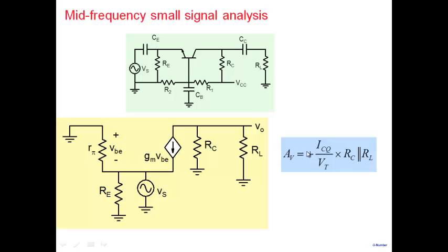phase. In common emitter, it was minus, which means input and output were 180 degrees out of phase. Here, they are in phase with each other. If you have a positive cycle here, you have a positive cycle here. So that's an amplifier in phase. Alright, so same as the CE amplifier, but it is non-inverting. Common emitter amplifier was inverting.